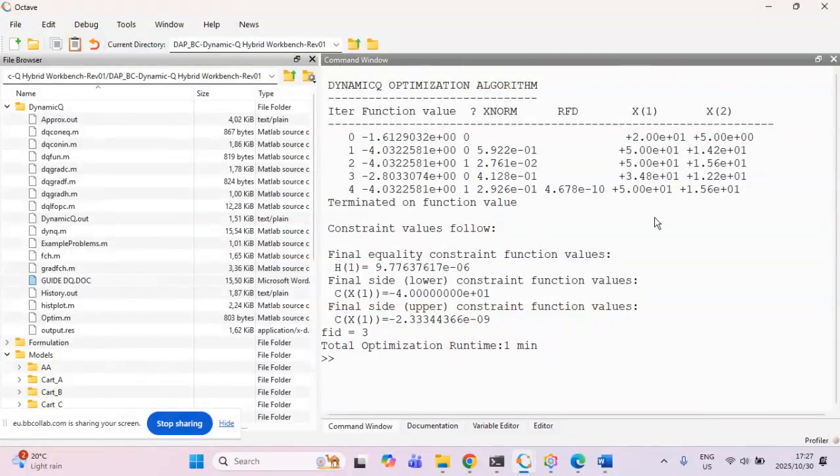So we have 50 Newton meters maximum torque, which will provide the maximum acceleration, combined with a 15.6 value on the aerodynamic damping coefficient. Now, if we look specifically at the maximum torque of the system, it does make sense that the higher the maximum torque rating of the motor is, the higher the acceleration is that I can reach in the system.